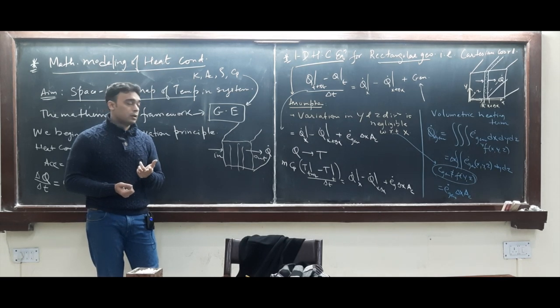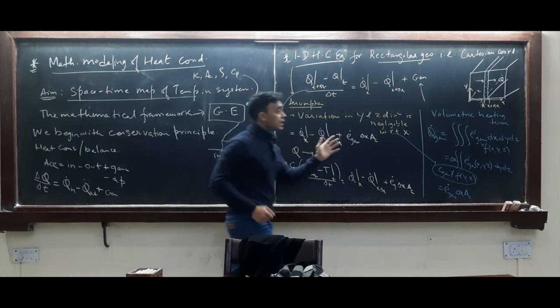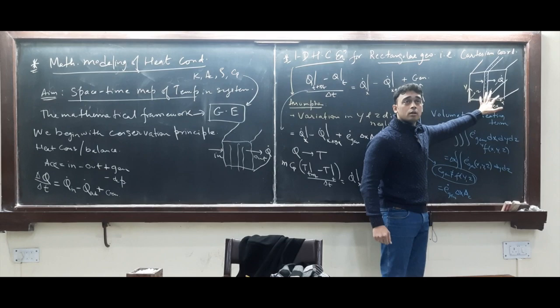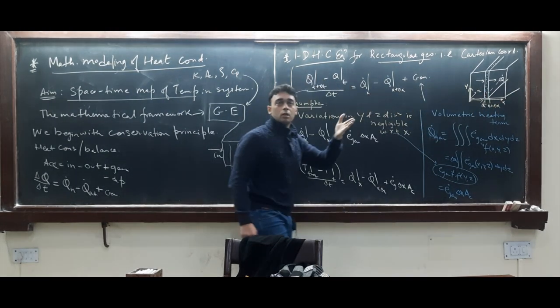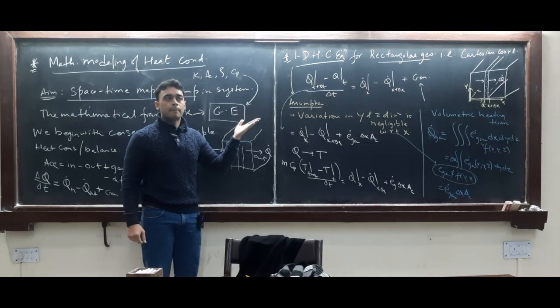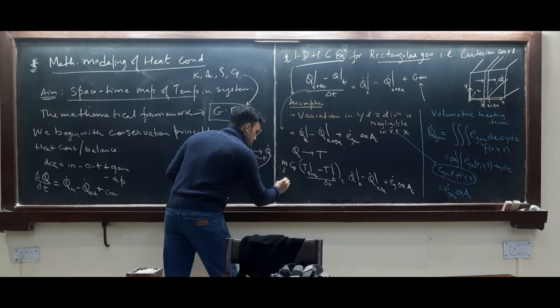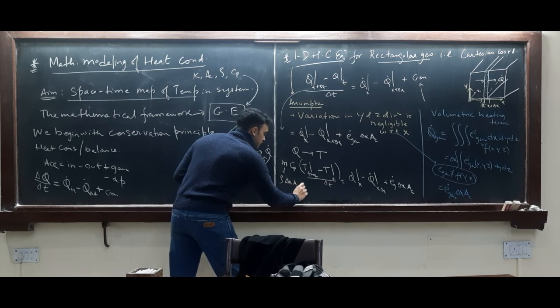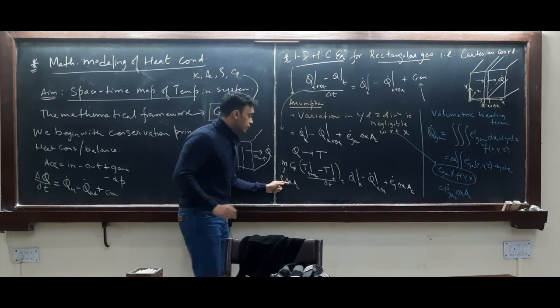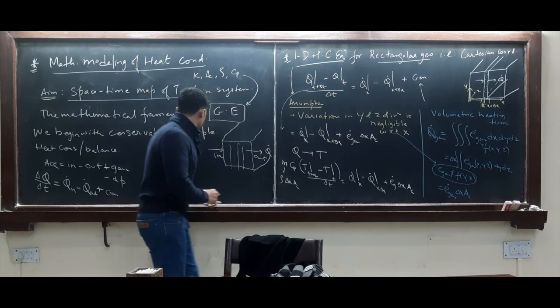Density. So mass can be written, this mass is for the entire block? Is it for the entire block? For the element. So we can write density into volume. What is the volume of the element? Delta x into A_c. So density into delta x into A_c, right? And now we can divide the entire equation by delta x into A_c. Let's see what we get.